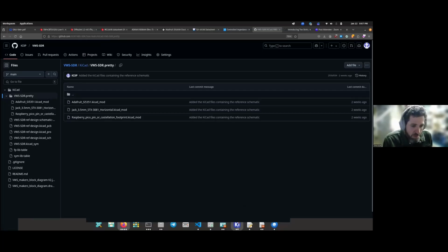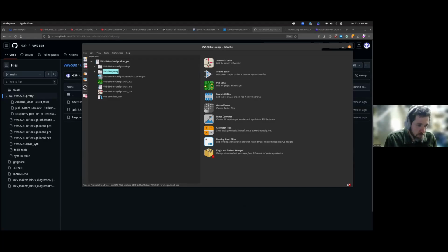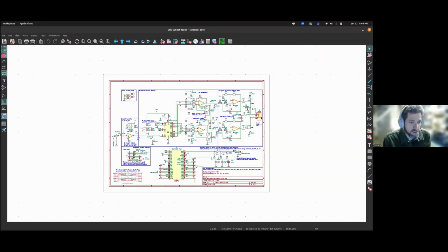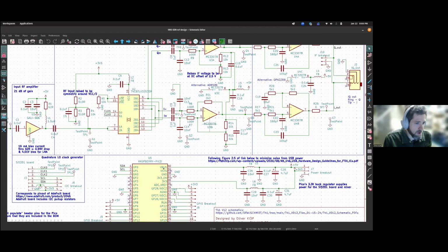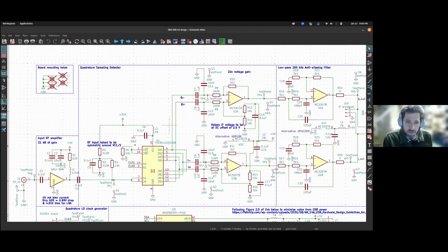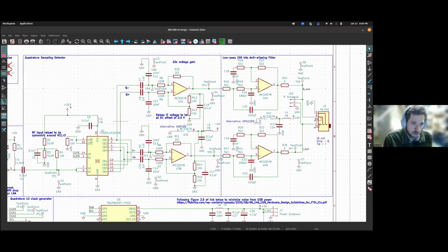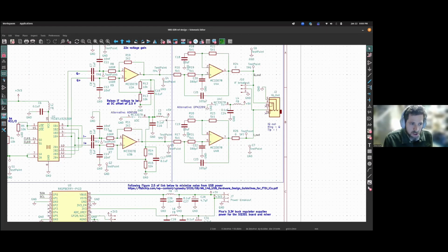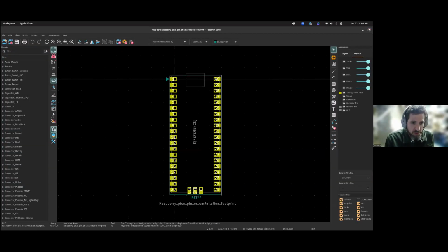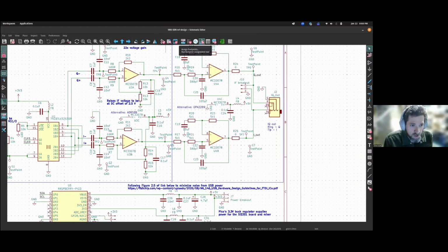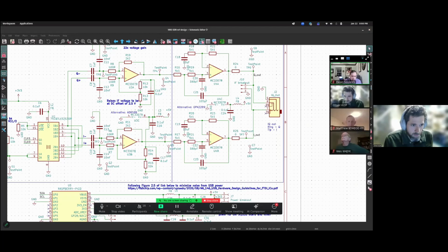Okay, so you open up the KiCad project. Open up the schematic. This is where we got to last time. We went through the steps of drawing this, fast forward to the end, and got to see the final product. So at this point, you have laid out the schematic, and you have gone through and run the footprint assignment tool, which is this one over here, Assign Footprints. You ran that, and hopefully it'll work this time. There we go.